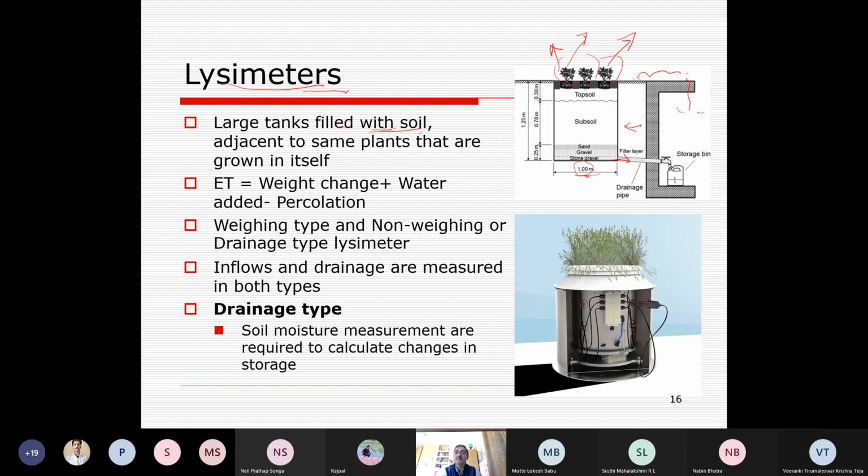So in real soil condition, water is lost into the atmosphere, that is evapotranspiration, or it moves laterally or maybe vertically. So if it is lateral, then it is in the same system. But if it is going deep, we have interest. Suppose the crop roots are going up to 1 meter, and if water is going beyond 1 meter, it has no use by the crop. So it is basically the drainage. So drainage here we are measuring as an output from this particular tank. How much is the loss of water as drainage? Then it is simply transferred in any other direction from this system.